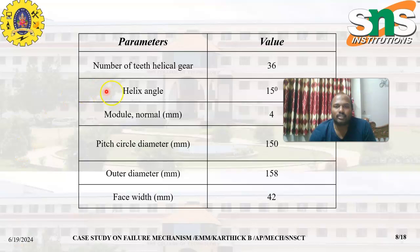The next are the common parameters. It is a 36 teeth helical gear. The helix angle is 15 degrees. The module is 4, pitch circle diameter is 150 mm, outer diameter is 150, face width is 42 mm. So this is a common helical gear.